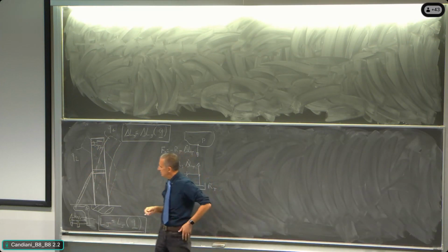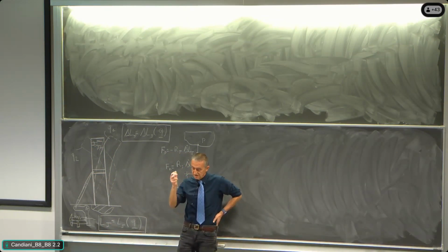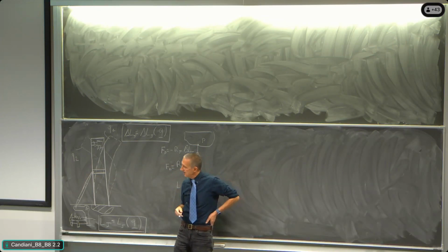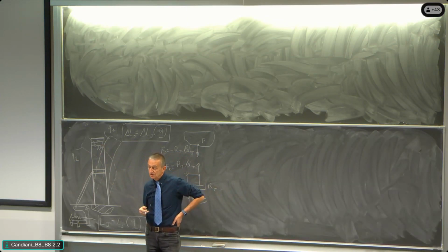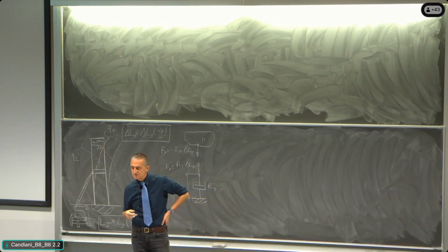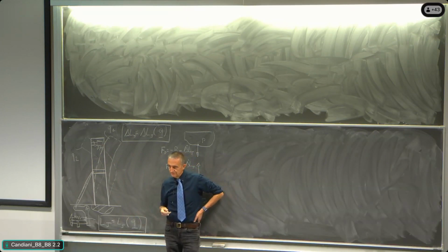And so usually the tall buildings that can be excited by the wind, like the Isozaki building, almost always have inside a tuned mass damper that is taking care of increasing the damping of the building, so that the vortex shedding excitation of the building is not making seasick the people who are living in the building.